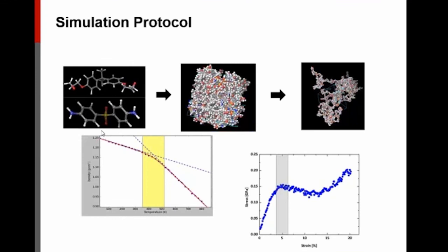Thank you, Joe. Great. So molecular dynamics is a technique that allows us to model the polymers at a molecular level. With that molecular level modeling, we can build a representative structure for the polymer material. What we're showing here is a thermoset resin. So you have a simple resin system with an epoxy and amine, and you can cross-link a collection of those monomers into a representative structure, and then you can interrogate the properties of that polymer system or that thermoset.